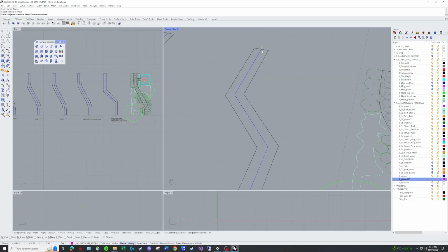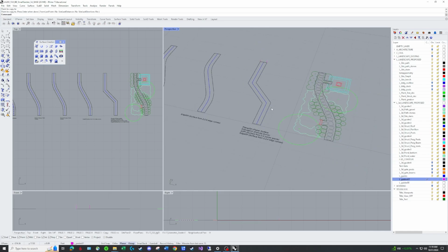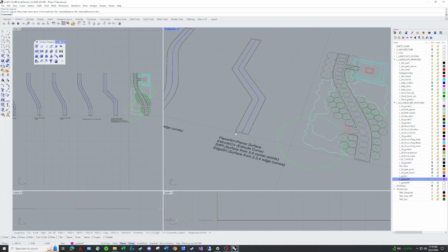So what I'll do is, usually we're building off the center line, but because I'm doing surface from four corner points, I actually want to go ahead and just move and copy these to the corner points. So what I know is these two corners will be 0. This will be 1.5. What I'm going to do, just to show you how it's done, is make these two corners, when we hit this corner, this is 6 inches, this is 1 foot. So it'll just sort of move uniformly up to the 18-inch height.